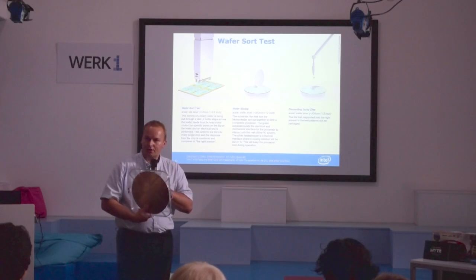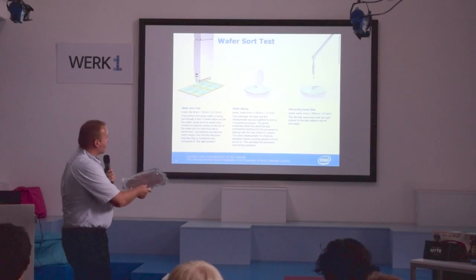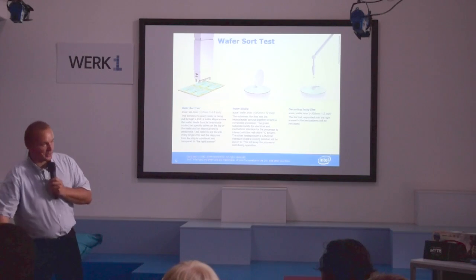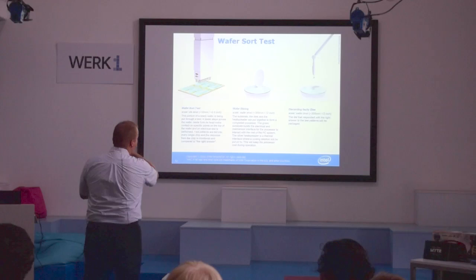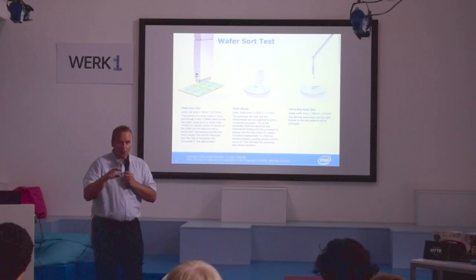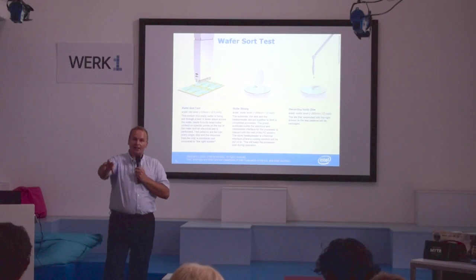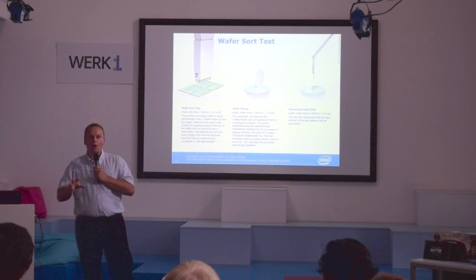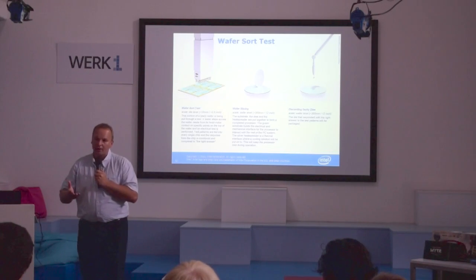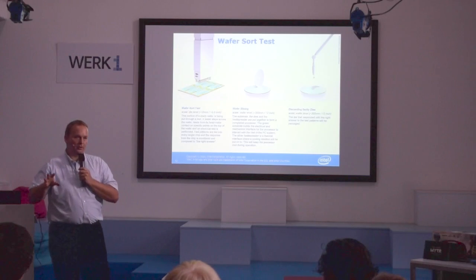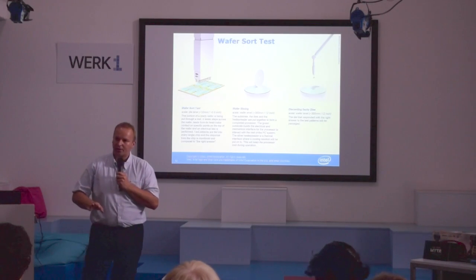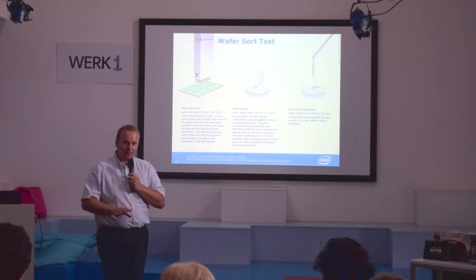We need to package it, and that's actually the next manufacturing steps that I'm explaining. So the left-hand picture basically shows that on the wafer, we're starting to test those dies because the process is so complex and it takes so long that not all dies are good. So we work towards so-called perfect wafers, and we sometimes get them.